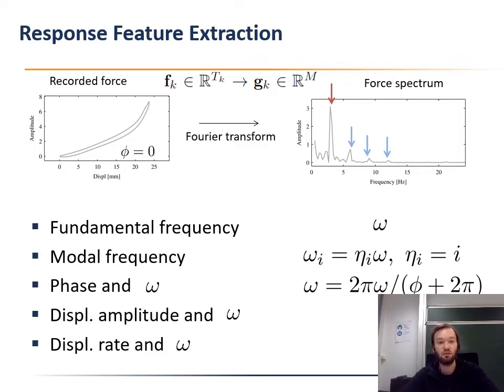Well, we look at what we recorded. For example, this is the amplitude of force, and this is the displacement. You see it behaves very nonlinearly. As the probe contacts the object and starts displacing it through the sensorized probe, we can see force increases. This is for synchronous compression at zero phase. It's basically like closing a gripper. And then when we reach maximum displacement, the tooltip retracts, and we obtain such a step. So this is recorded, as I said, at phase equal to 0.